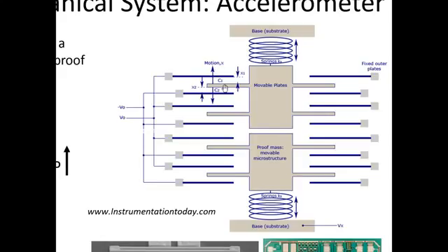At the same time, the second capacitance is going to decrease. So you have one capacitance that gets larger, another capacitance that gets smaller. This is a differential way of sensing. It's a very accurate way of doing things. It's very good at rejecting noise. So they have some differential sensing element here, and the other legs of the capacitor work the same way.